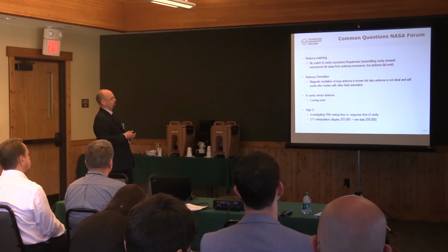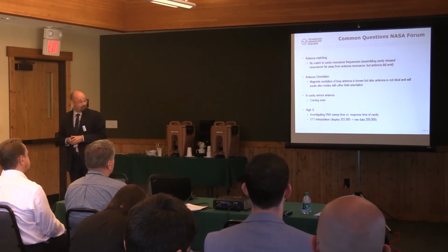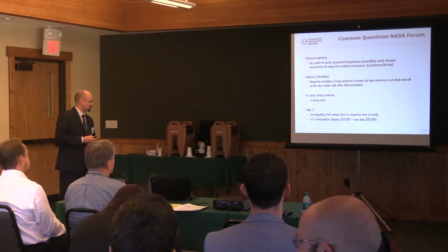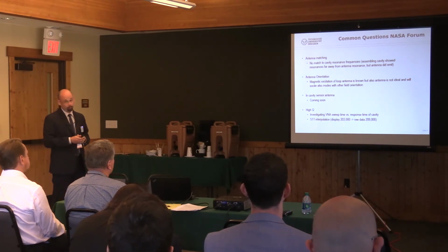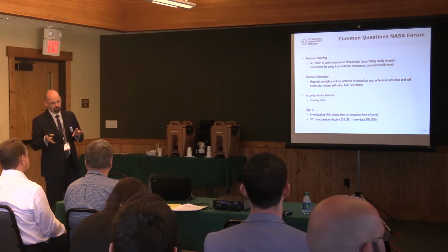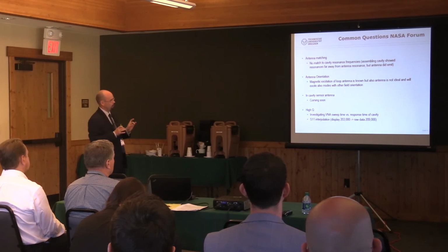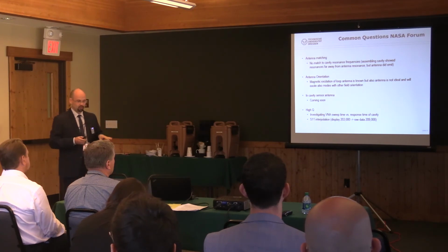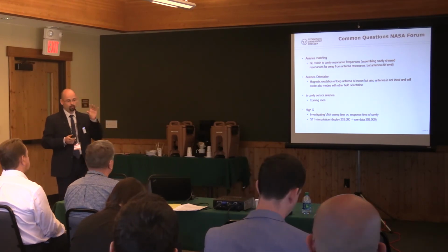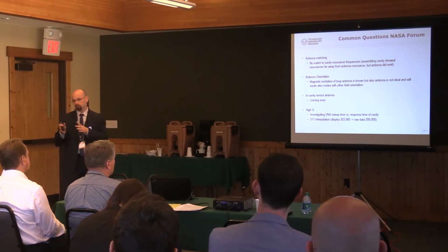Well, let's talk about some of the common questions from our NASA Spaceflight Forum, which were addressed very often. One point was matching the antenna to our cavity. As I already said, in these first trials, I designed my antenna for a certain range of 2 gigahertz, and although it was designed for 2 gigahertz with the reflection peak at 2 gigahertz, it also radiated at 1.8 or 2.2 gigahertz.